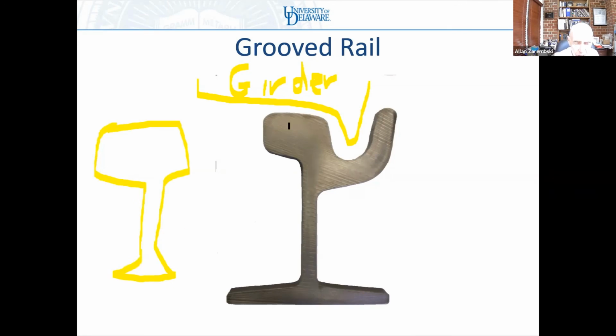In fact, the head of the rail can bend if it's not supported. If you look at where girder rail is used, you'll always see that it's usually used in embedded track. That's where the most common uses are: light rail or trolley systems, light rail systems, LRTs.